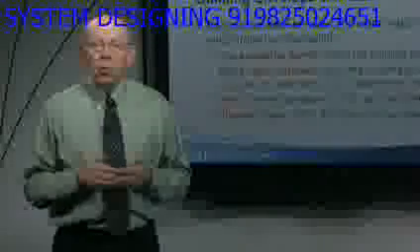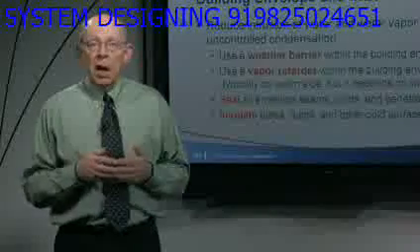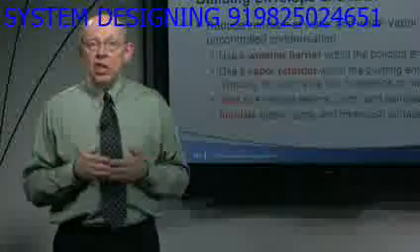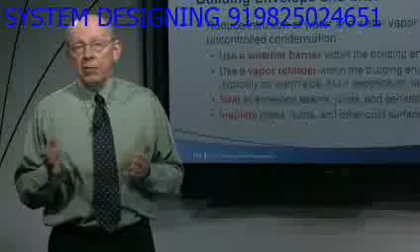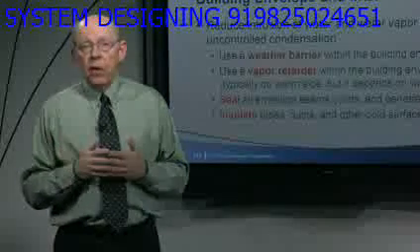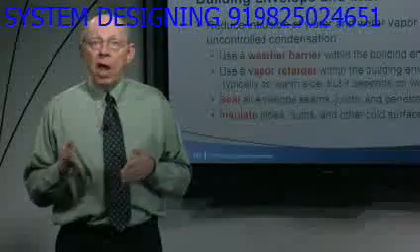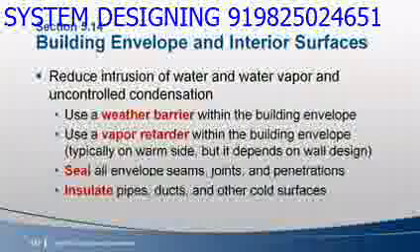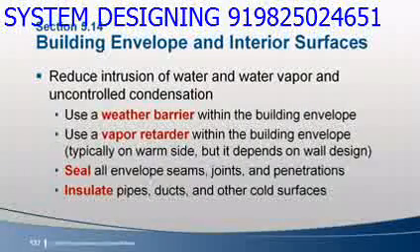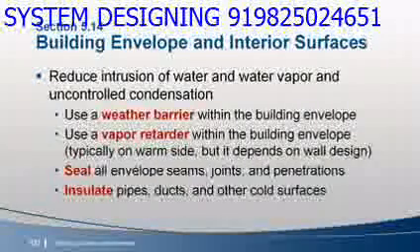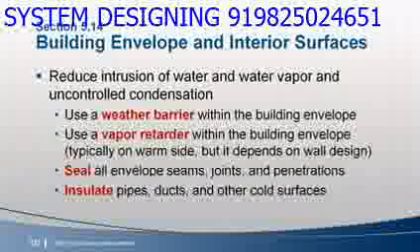Section 514 reduces water intrusion into the building, as well as unplanned condensation on cold surfaces. The building envelope, including walls and roof, must be designed using a weather barrier to prevent the intrusion of water and airborne contaminants. And a vapor retarding surface must be installed on the warm side of the insulation to prevent condensation of water vapor within the building envelope. And all exterior joints, seams, and penetrations must be sealed, forming a continuous barrier to prevent air leakage.